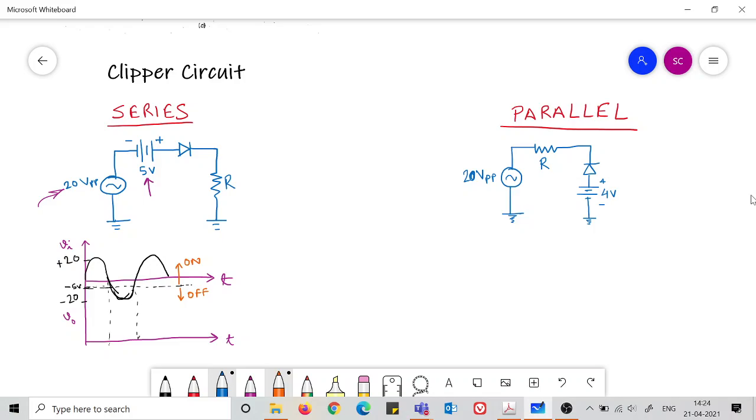This is the first step. So the range of values of the input voltage where the diode is forward biased and the range of values when it is reverse biased. When this is clearly identified, now we apply one of the approximations, and we apply the ideal approximation if nothing is told to us. Then if this is ideal approximation, then this is short, and when this is shorted,